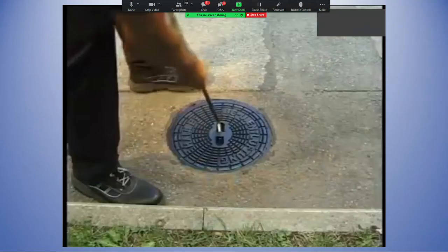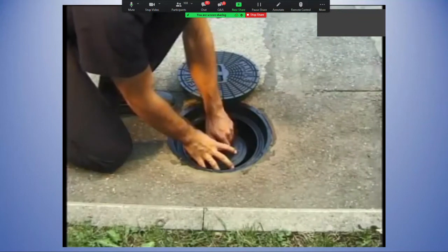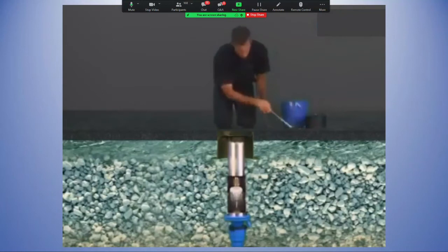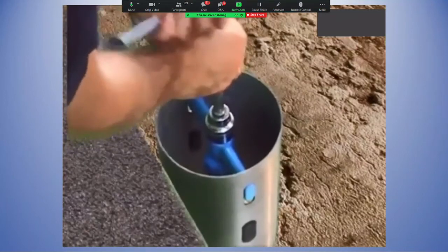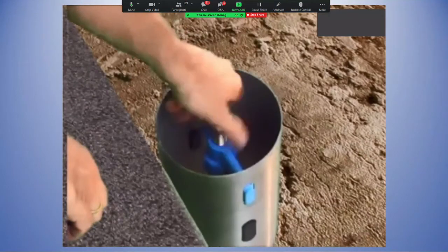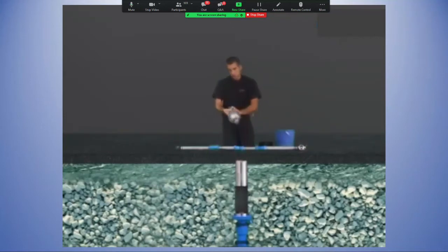This video should play. This is just a real example, a cross-sectional view of what the operator is doing. So again, the dust cap's removed, and as you see, he's going to take a ratchet and loosen that centering bolt that lifts the yoke. You can see the valve lifting, and that's the self-sealing tappet with the water pushing it out. As he pulls that valve out, there's going to be residual water left in there. It has a drain cock in it as well, and that drains back to nature. Now the valve is ready for whatever inspection or maintenance might be required.